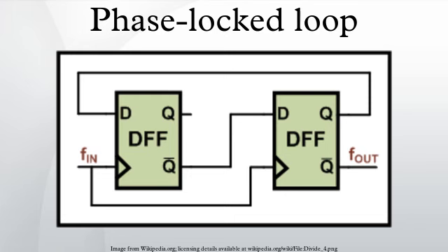In practice, one would likely insert other operations into the feedback of this phase-locked loop. For example, if the phase-locked loop were to implement a frequency multiplier, the oscillator signal could be divided in frequency before it is compared to the reference signal.